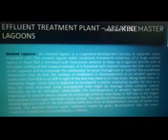The significant difference between the ASP and aerated lagoons is that the final settling tanks and sludge recirculation activities are missing. The aerated lagoon water treatment may be followed by a maturation pond for further treatment, as shown below. In aerated lagoons, the effluents from the primary treatment process are collected in tanks or lagoons.